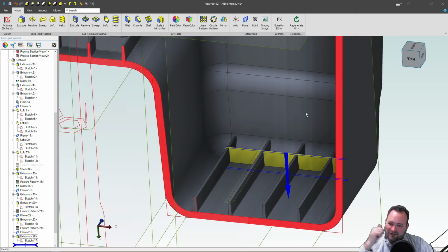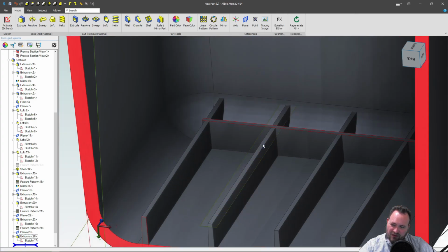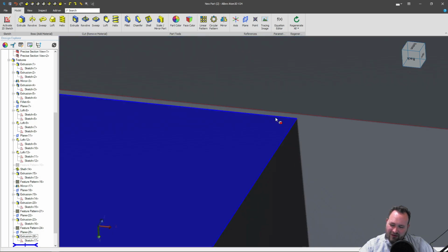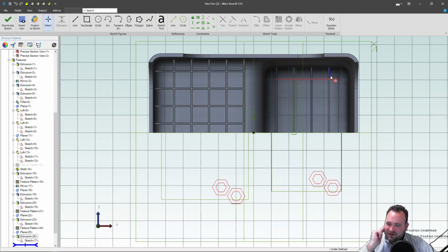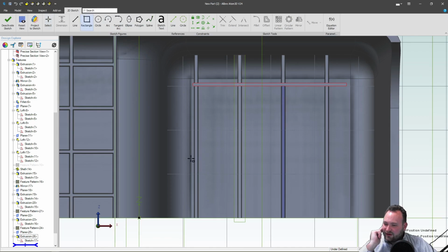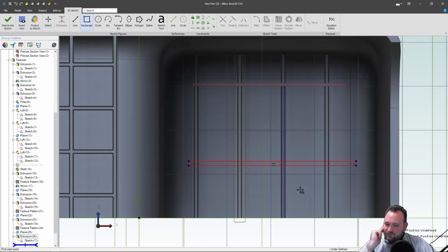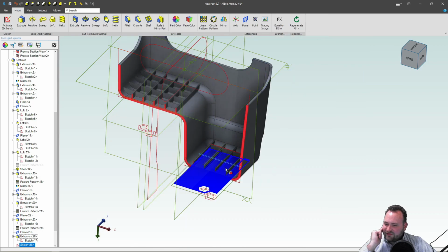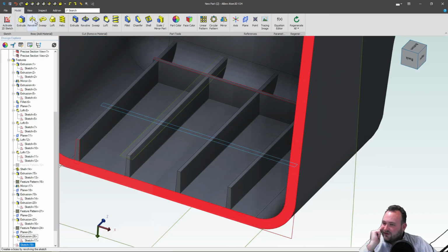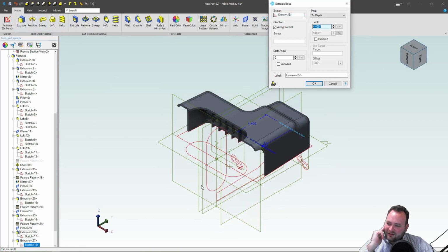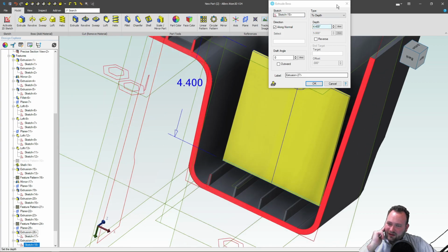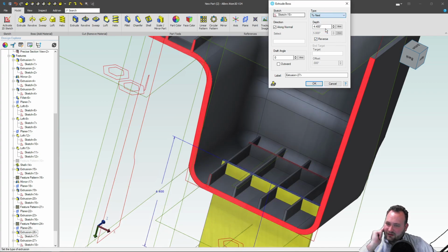And that's looking good. So the question is, why did I create a plane and go 1,000th above? Well, if I choose this face, activate a sketch, and I create a cross rib going right across it, deactivate my sketch here. So my cross rib is the exact same height as the other one. We're going to go to extrude. Again, I'm enjoying these faster rebuilds. We're going to go to reverse, to next.